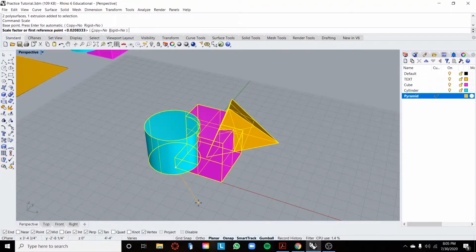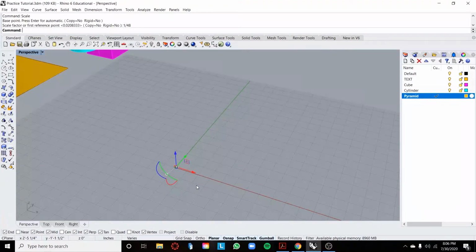And say we need to create a drawing that is at a 1/4 inch scale. An easy way to remember how to do this is to invert the fraction and then multiply it by 12. So 1 foot equals a quarter inch. We'll invert a quarter inch, so that gives you 4. Multiply that by 12 and you get 48. And that will be our scale factor. However, we're going to be scaling down, so we're going to want to type in 1 over 48.